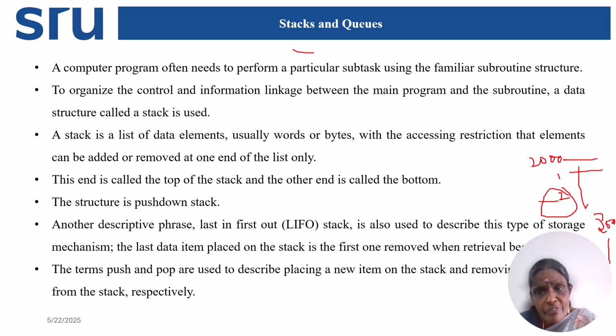For that, before going to memory location 3000, this 2002 will be stored in the stack. After that, it will go to 3000. After seeing RET, the control will go to the stack, take 2002, and come back to 2002. In this way, a special feature is seen for the stack memory location, and for this special occasion the stack memory operation is utilized.